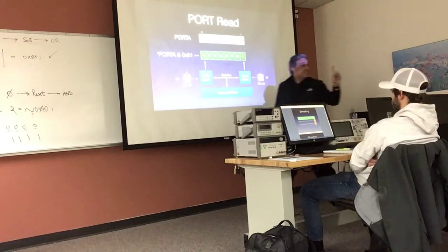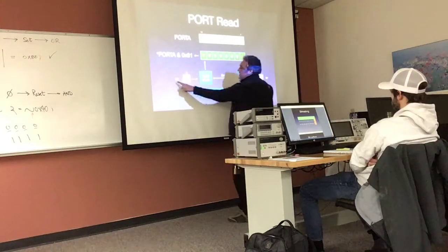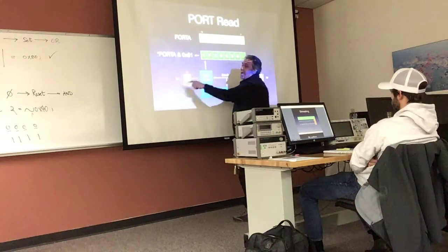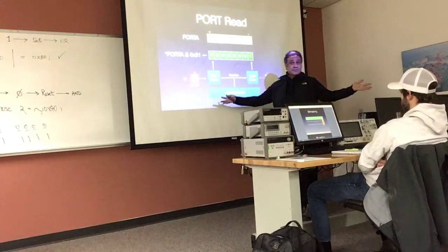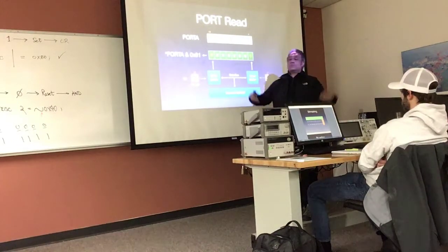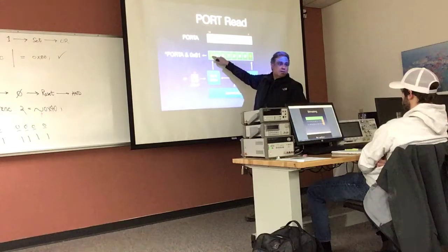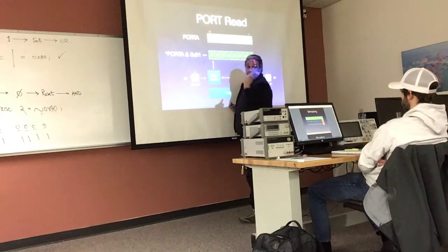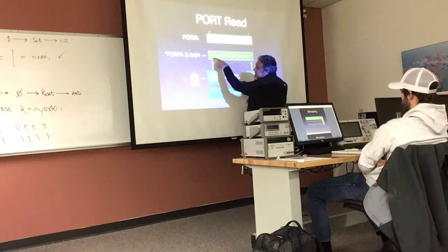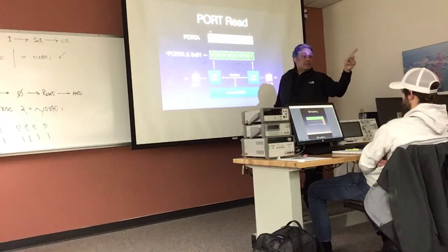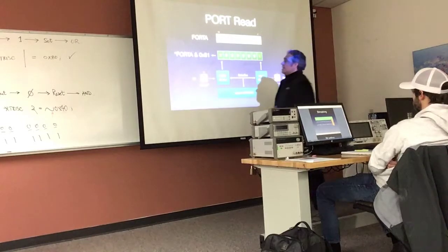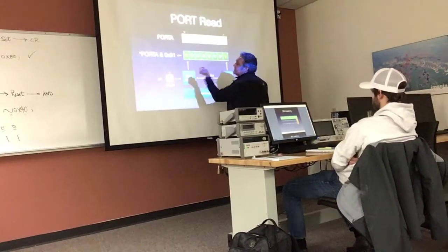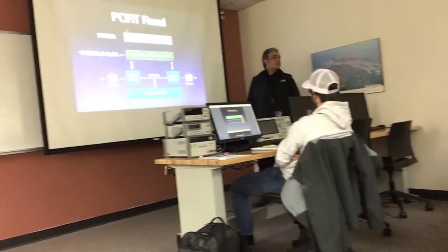And then, listen to what I'm going to say now, because this is very important. This behavior is not set up by you. In other words, this is going to happen because it is a circuit. There's no software that I need to do to pass the data all the way to the port. It will happen by itself. The moment that I make my tri-state an input, you put 0 volts, and this will become a 0. And at any moment when you are ready, if this instruction coincides with this moment in time, I will see that 0 coming through my software.